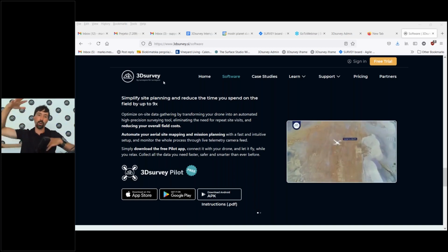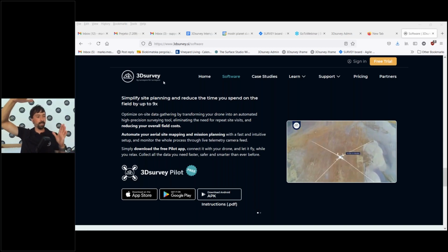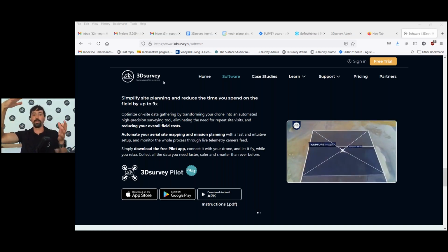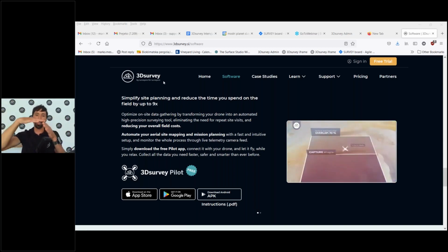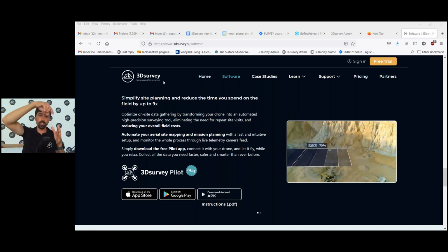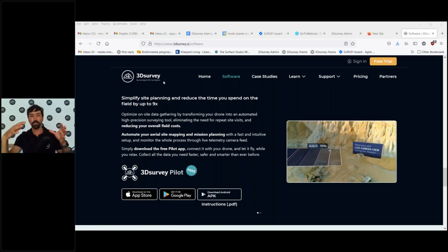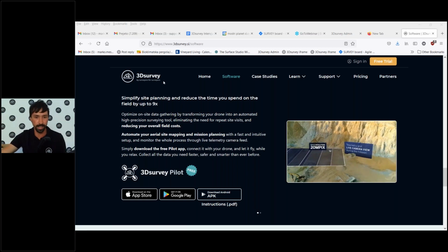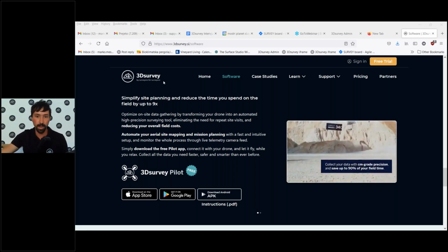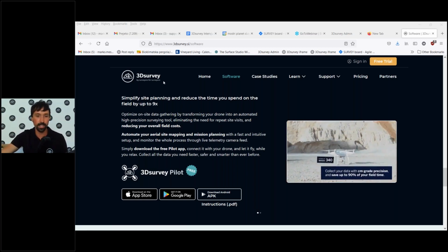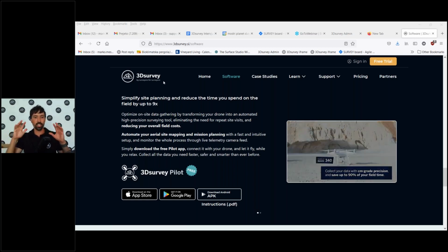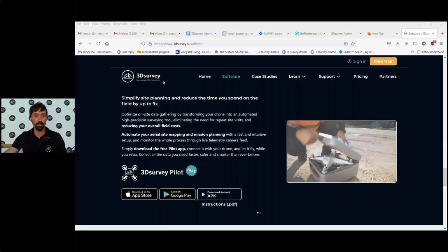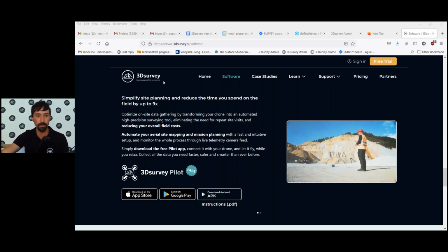You cannot go with a grid mission and then immediately side images from the building. So this is not going to go together. You will need some circles or nadir images to connect them, same as I explained here. Maybe I didn't understand your question 100%. If you need additional explanations, please send me your question at support@3dsurvey.si.